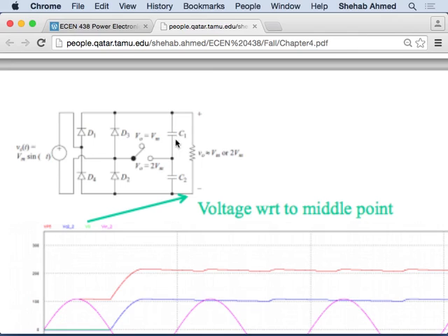Simple full wave, just like we just covered. When the switch is closed, what's going to happen? In the positive half cycle, I do the same thing that the previous circuit was doing. Through diode D1, I'm charging capacitor 1, and current is flowing back to my source.